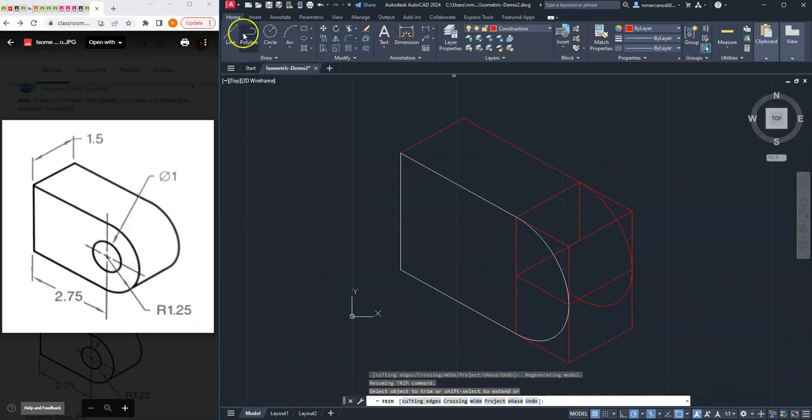Okay, so the one line I do need is my perpendicular bisector. I'm going to click from the center to the diagonal to the end point, and where it intersects here is where I'm going to create my line that goes across. So I'm going to go to Object, from this point until it snaps here, and you can also make sure that it is 30 degrees, and I can now trim this line and this line, and we can select this line and go to Object Line to define it.